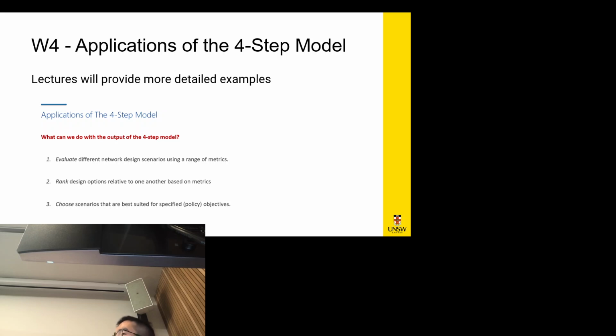The third step is, how am I going to get there? We looked at utility and we looked at the formula to figure out the modal probability, like the modal proportion. So let's say, for example, 70% on cars, 20% on public transport, 10% riding a bike. And then step number 4 is, which network should I take if I drive, for example?